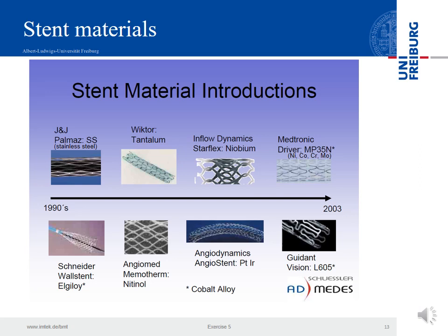There are woven approaches, there's something like platinum iridium, or we have MP35N, that's also a very well known cobalt alloy from cardiac pacemakers that is very corrosion resistant. Or some other alloys depending on the secret recipes of the manufacturers.